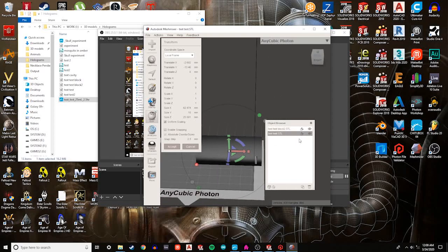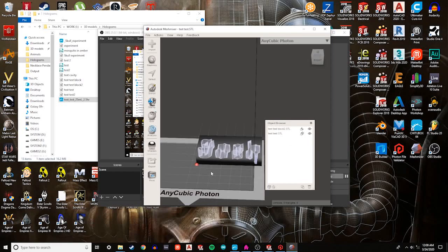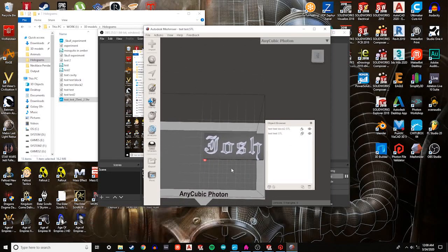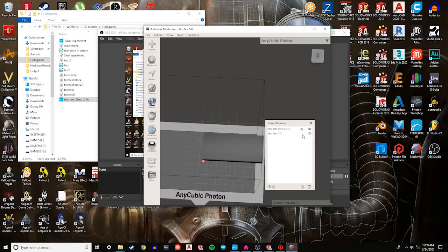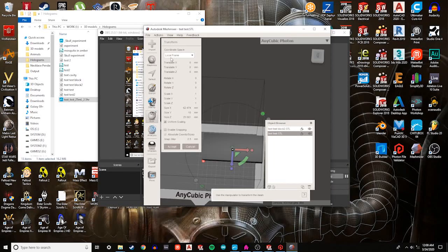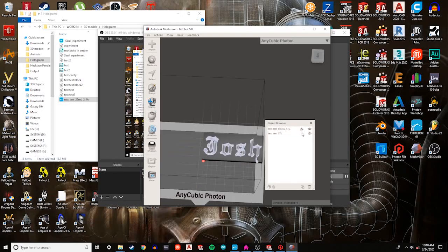And so what you can do is click on this magnet, and you can see right through there, kind of an X-ray view. Make sure that it's centered. You can probably go a little bit to the right. Select it, edit, transform. You can use the arrows, or you can type it in up here. You can also use it to rotate and scale. That's all within this tool. And now we check it. Looks good to me. Make sure that magnet is unselected when we go ahead and do this.